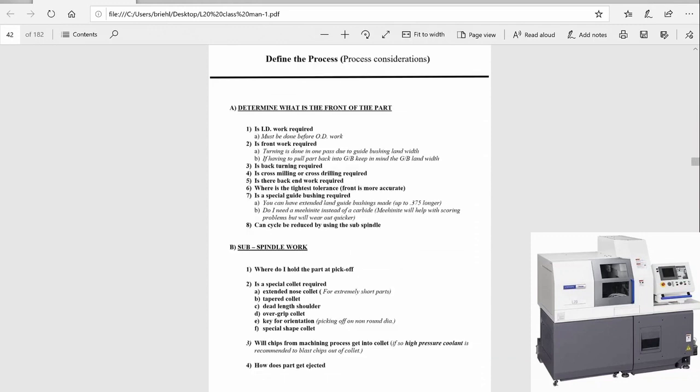There are many factors that determine which way the part is processed. Most of the time, the determining factor is which diameter on the part is best to clamp on with the back spindle collet. When determining our machining process, our goal is to split up our main and back spindle time as equally as possible without compromising any features or tolerance required by the part drawing.